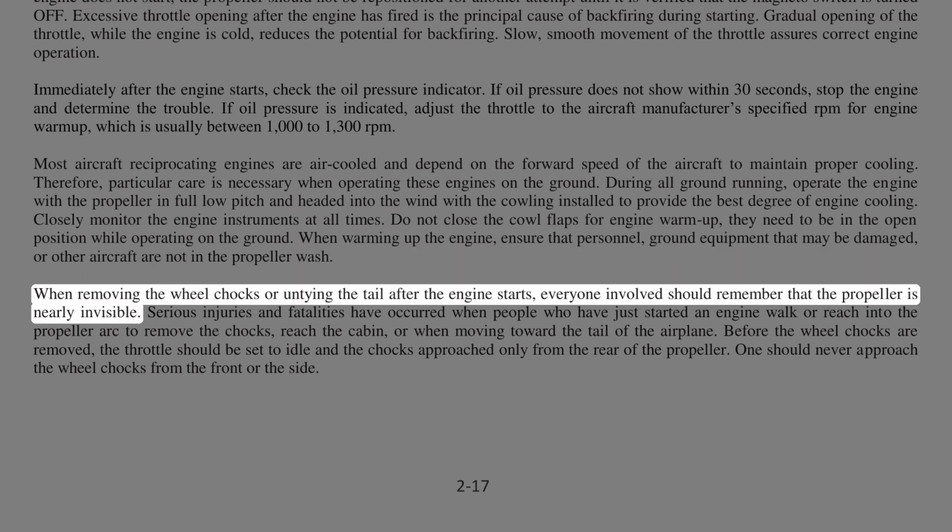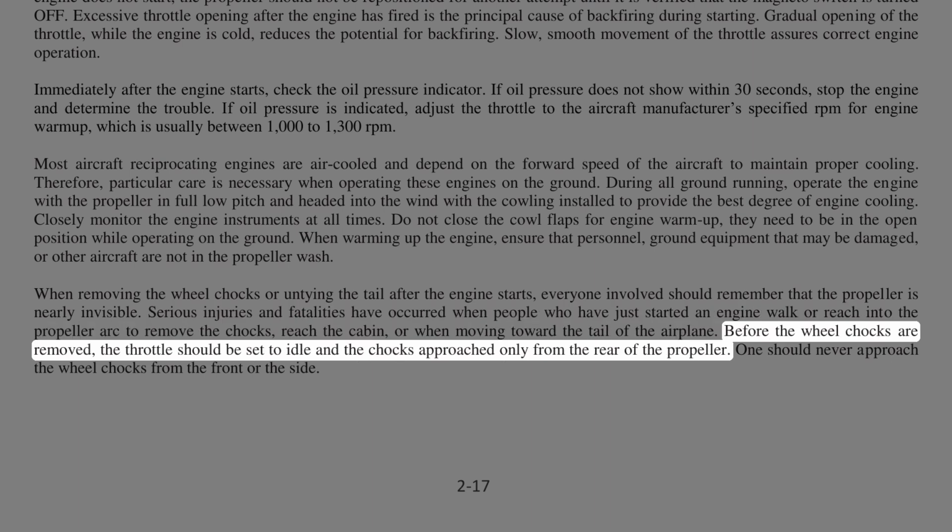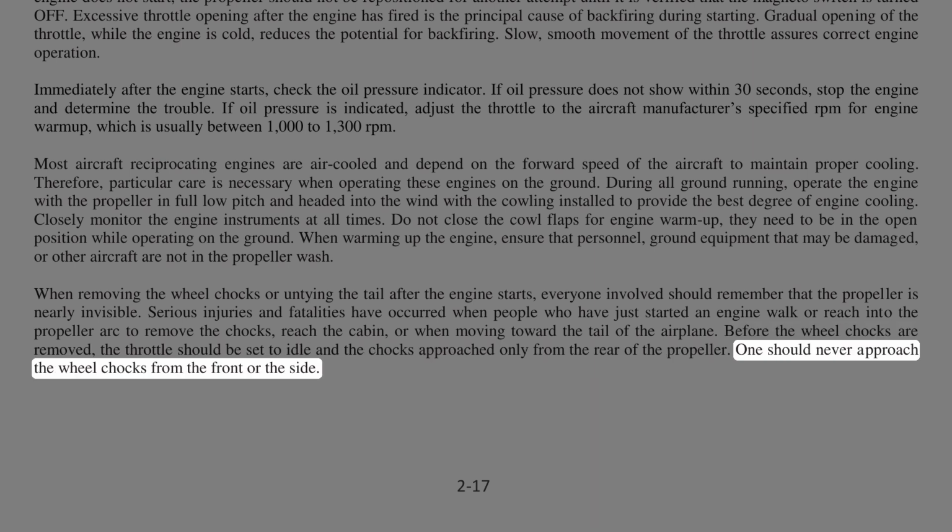When removing the wheel chocks or untying the tail after the engine starts, everyone involved should remember that the propeller is nearly invisible. Serious injuries and fatalities have occurred when people who have just started an engine walk or reach into the propeller arc to remove the chocks, reach the cabin, or when moving toward the tail of the airplane. Before the wheel chocks are removed, the throttle should be set to idle and the chocks approached only from the rear of the propeller. One should never approach the wheel chocks from the front or the side.